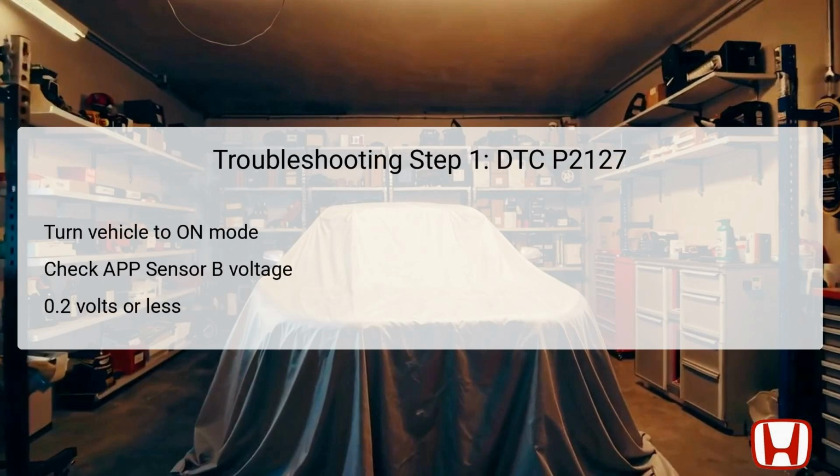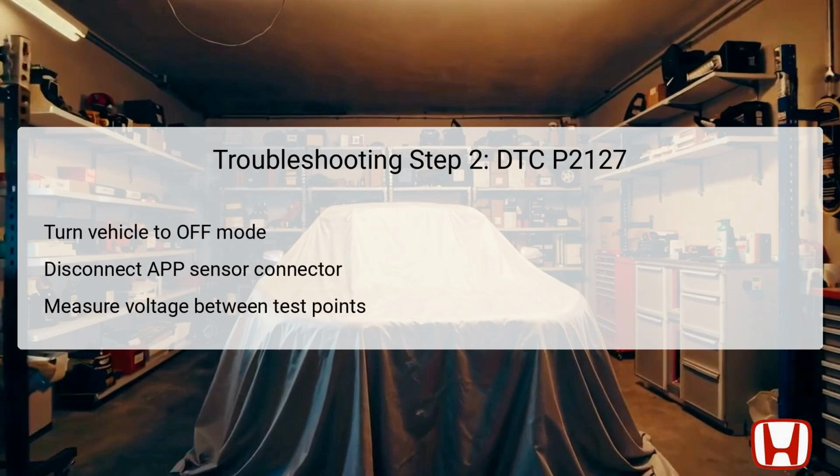In the first troubleshooting step for DTC P2127, you need to turn the vehicle's ignition to the on position without starting the engine. With the Honda Diagnostic System HDS tool, check the voltage level being reported by APP sensor B. The threshold voltage is the check for the second troubleshooting step.